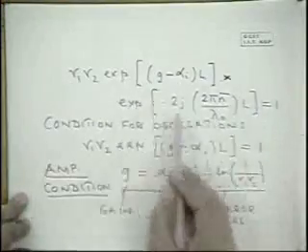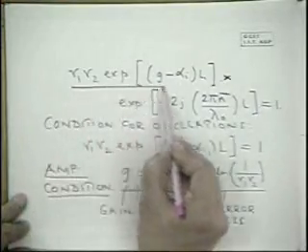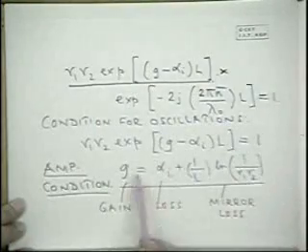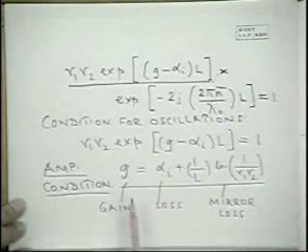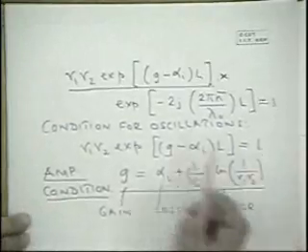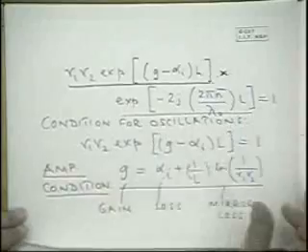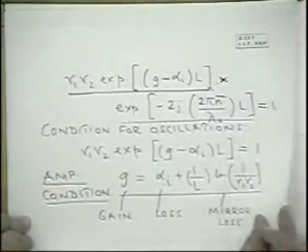Okay, we have just examined this part of the expression. That is, the amplitude of the feedback, the gain, must be enough to offset the losses. What is the phase condition? The phase condition is connected with this. The feedback must be in phase. It's coherent oscillation. Okay, so the feedback must be in phase.